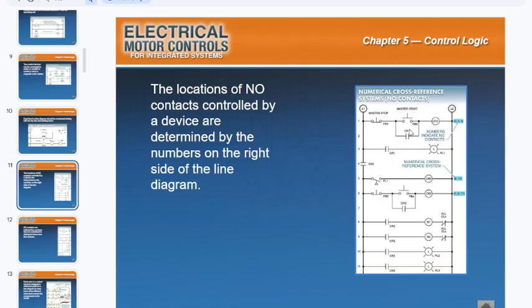And if you look at rung 2, there's CR1 normally open contact. If you look at rung 3 ahead of that light, CR1 normally open contact. And I almost want to set this book on fire for doing this number 4 right here on the L1. This is so poorly structured, but fine. I'll accept it because that's not a rung. That is just L1 and they've placed a contact on it, but not to get so upset about things. Just calm down here. But same thing is going on rung 5, CR2, 8 and 10.